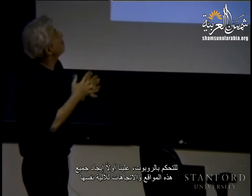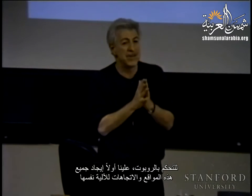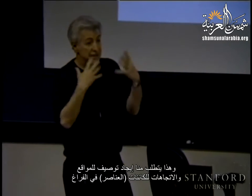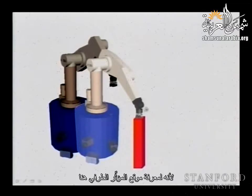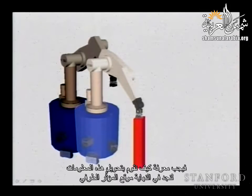So to control the robot, first you need to find the position and orientation of the mechanism itself. And that requires us to find descriptions of position and orientation of objects in space. Then we need to deal with the transformation between frames attached to these different objects. Because to know where this end effector is, if you know the positions of those different objects, you need to know how to transform those descriptions to finally find the position of your end effector.